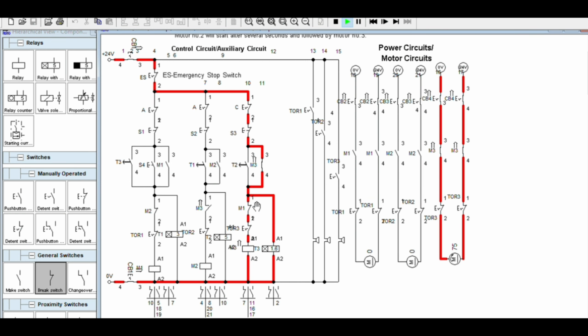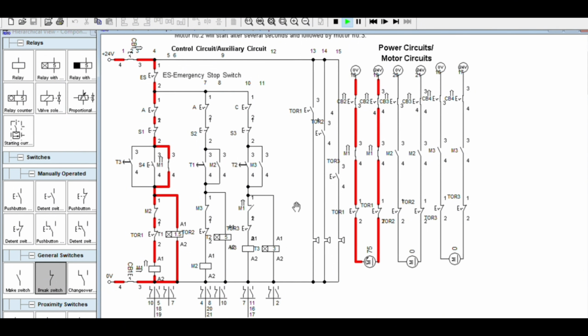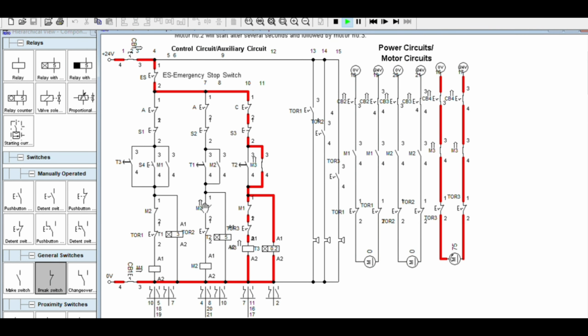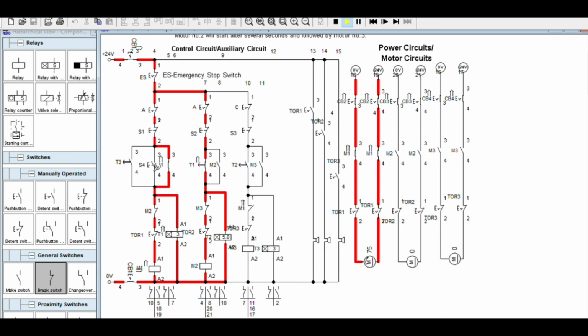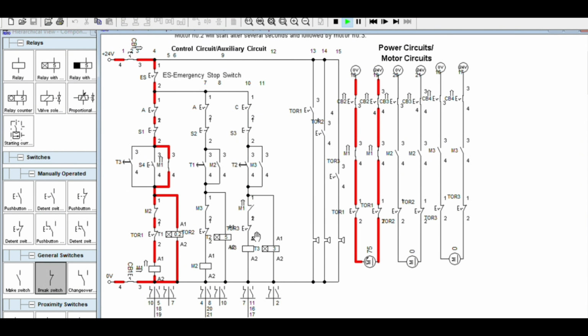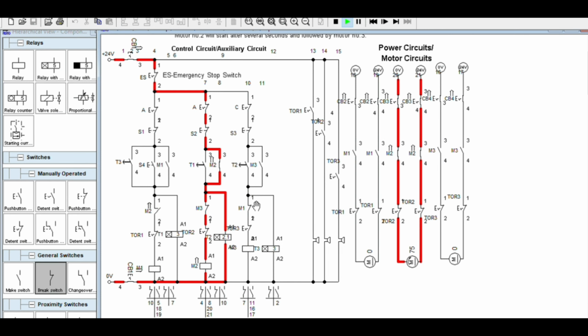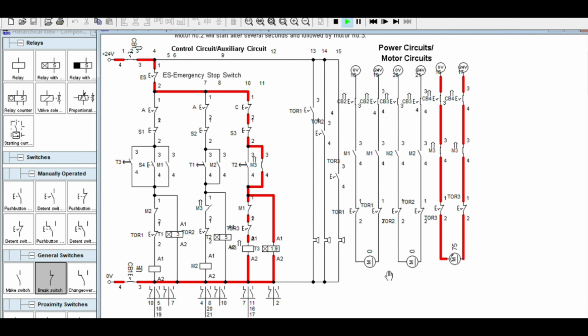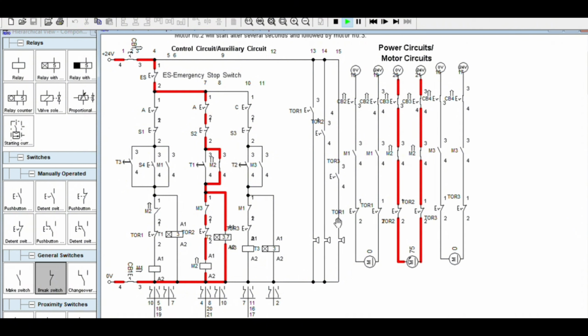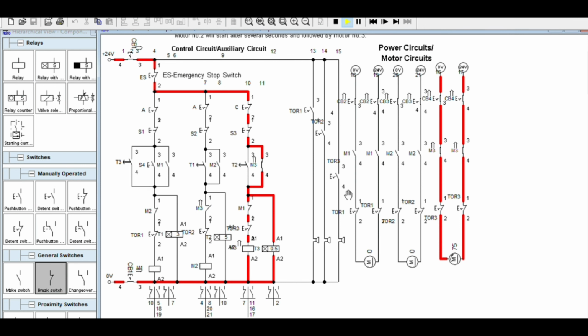There will be some problem in reality if you apply this in, let's say, forward reverse, where you have complex wiring. You should open this one first before turning this one on. So that means you will have that circuit. See, this one is opened only by this one. You cannot see it here, but in actual use sometimes there will be a short circuit if you have complex wiring here of forward reverse, or line 1 and line 2 will connect together.